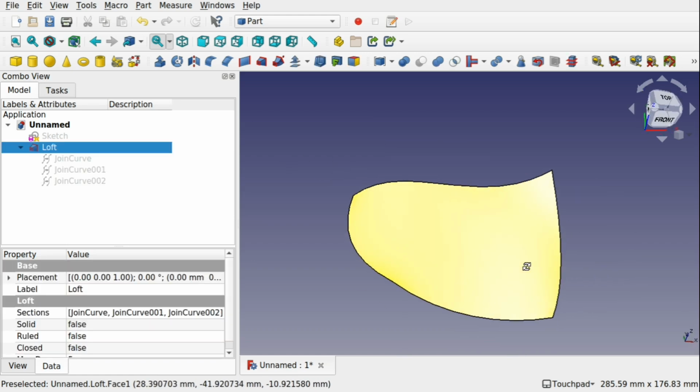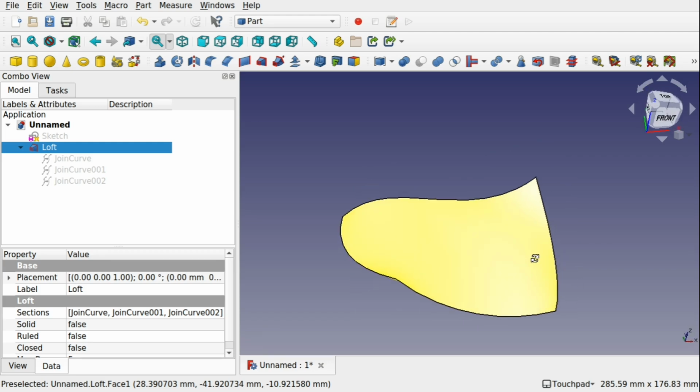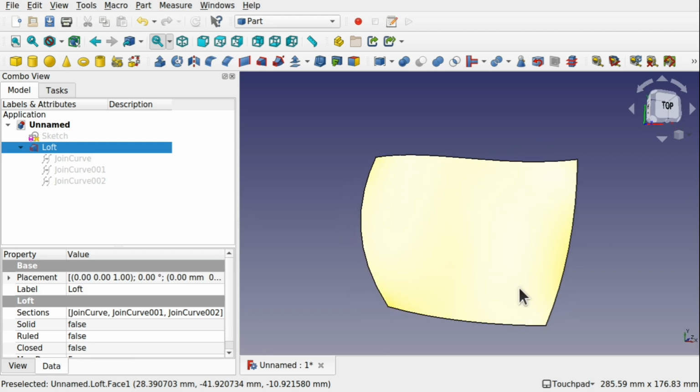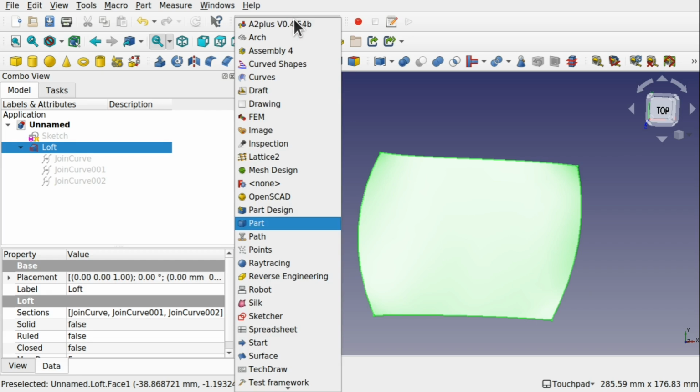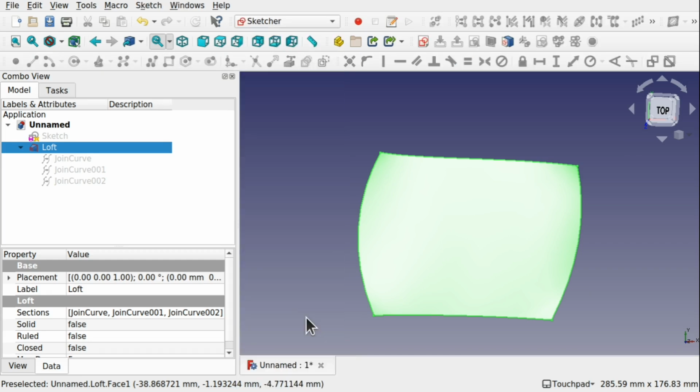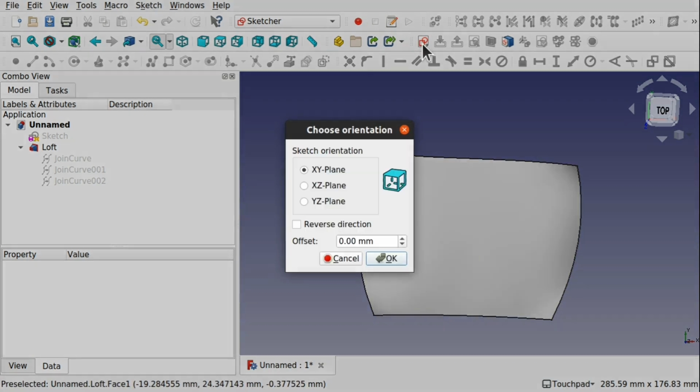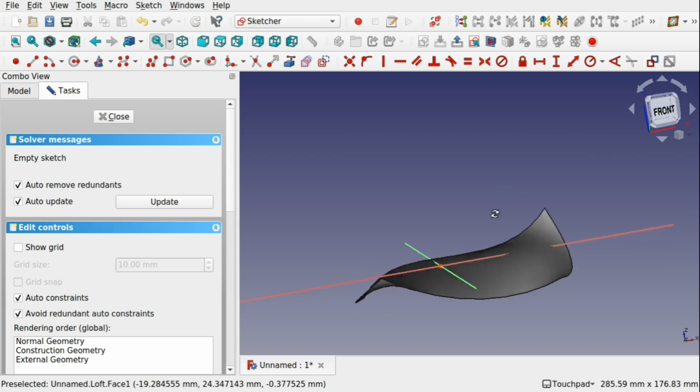We're going to create a pipe shell now, and I'm going to decide where the pipe shell is going to go. So I'm going to put it somewhere in the middle. So somewhere here. For that, I'm going to come over to the sketcher. I'm going to create a sketch, but I'm not going to attach it to this surface. I'm just going to create a sketch. You can play with the different types of attachment. You can use a datum plane if you want it attached to there. But I'm just going to demonstrate the technique, and it's up to you to modify it to your liking.